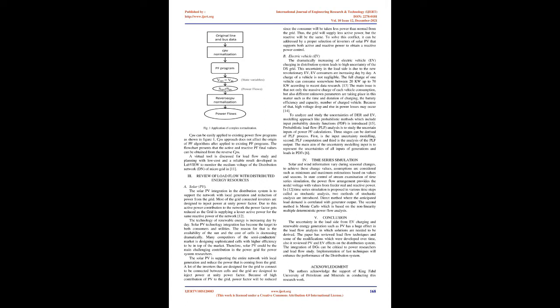LabVIEW to monitor the medium voltage of the distribution network, DN, of microgrid. 11.3 Review of load flow with distributed energy resources. A. Solar PV. The solar PV integration in the distribution system is to support the network with local generation and reduction of power from the grid. Most of the grid-connected inverters are designed to inject power at unity power factor. Due to this active power contribution to the network, the power factor gets reduced as the grid is supplying a lesser active power for the same reactive power of the network. 12.